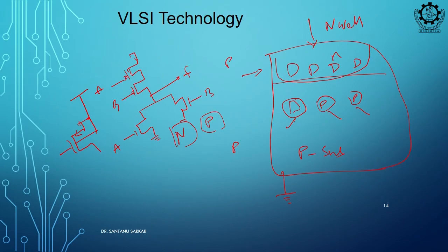Okay. In this case, this substrate you can short with the source because it is VDD, no problem. Now, you have two options for this bulk: one is you short it with VDD, or if you use two PMOS in the same global well, you can do that, or you can have a separate well for this M1 and M2, right.